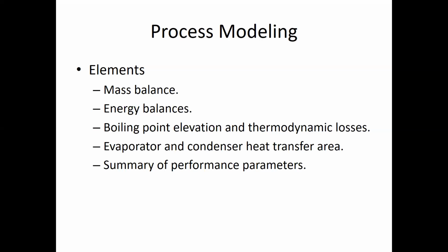The boiling point elevation is again a point that we consider because it takes care of the difference between the saturation temperature of salty water versus pure vapor, so that it helps us determine precisely the vapor temperature which is leaving the evaporator, for example.